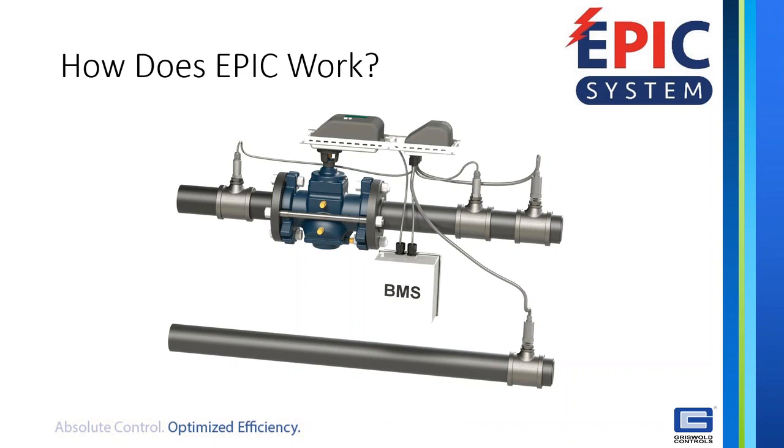When the load changes, that's a different situation. When there's a load change, maybe there's more heating or cooling requirements, there's some thermostat on the wall, it's going to sense the load change, or the building management system. And so when the thermostat is adjusted, it's going to change the coil's airflow. And as that airflow changes, the delta T of the water changes. So again, that's what we're measuring. The temperature sensors read the change in the delta T, and the EPIC brain, the controller, controls the valve to adjust the delta T back to the design.